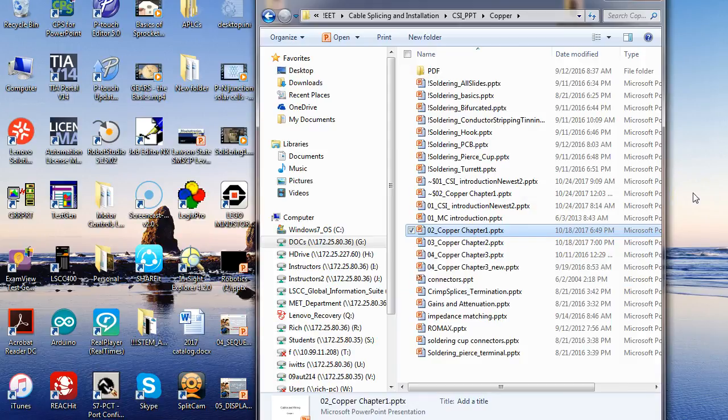I think that box over there has a caliper inside, and it has a dial mic, which we use to measure thicknesses and stuff like that. An outside mic, which is what we've got, has two jaws on it, and one of them's adjustable and one of them's not. It's stationary. What we do is we have a dial that we turn until it touches. And the ones we got, by the way, are not digital.